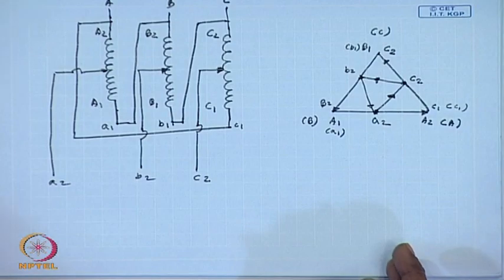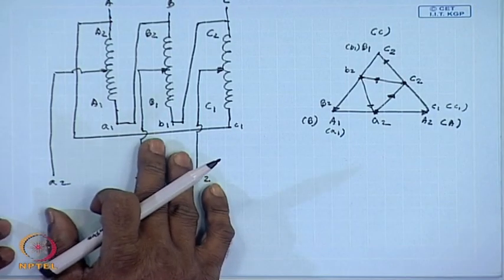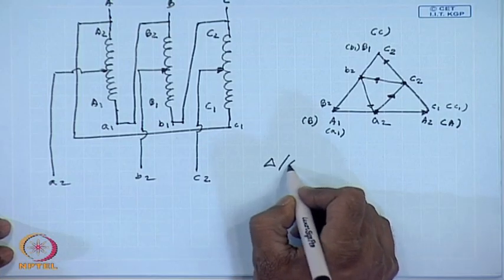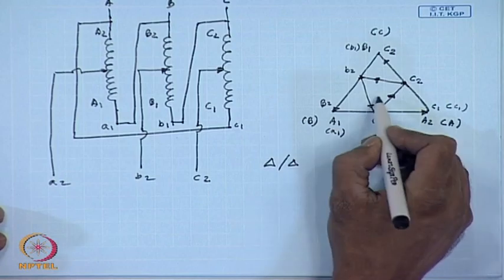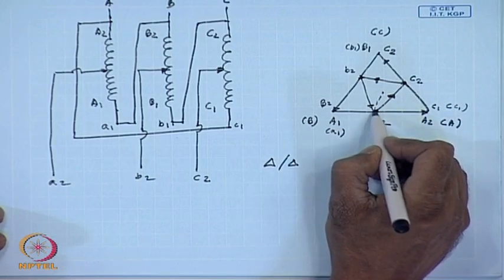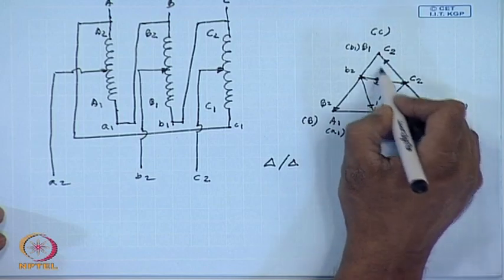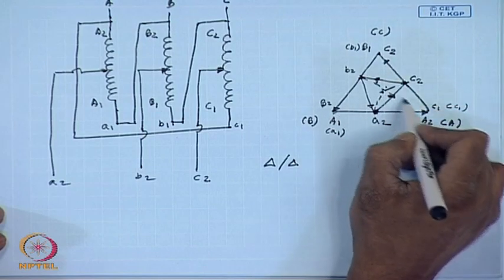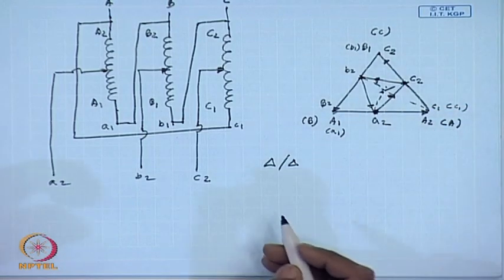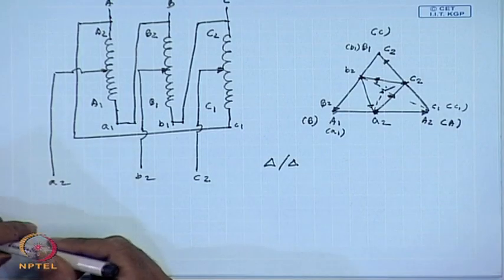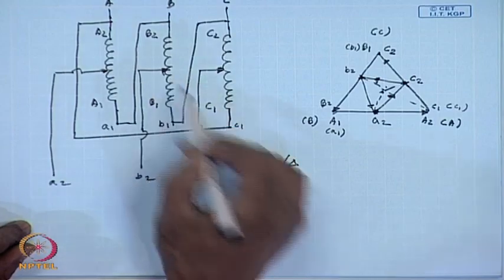However, when a similar arrangement is made with a delta connected auto transformer, we see that the angle between the line to neutral voltage phasor of the HV and LV side actually depends on the position of the tapping.